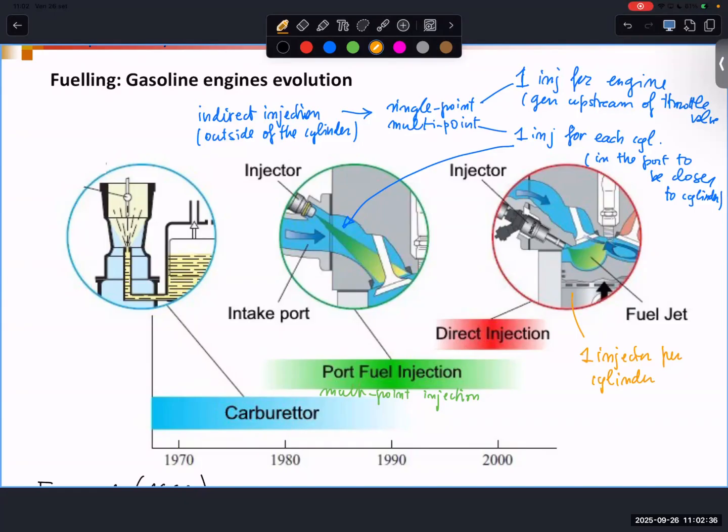It is not always the case, but we can consider that most of the turbocharged gasoline engines are direct injection, and most of the naturally aspirated are port injection, but you can also find mixed cases. To increase the advantages of turbocharging, it is generally matched with direct injection. Not the only possibility, but the most frequent.